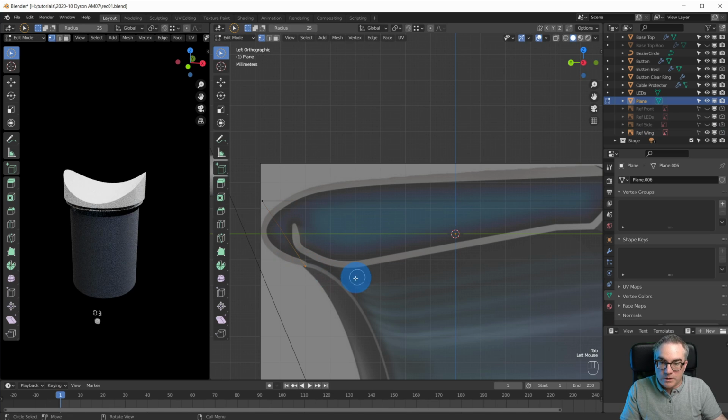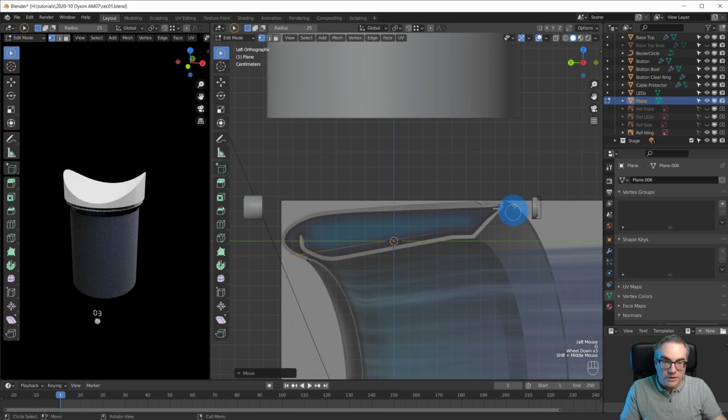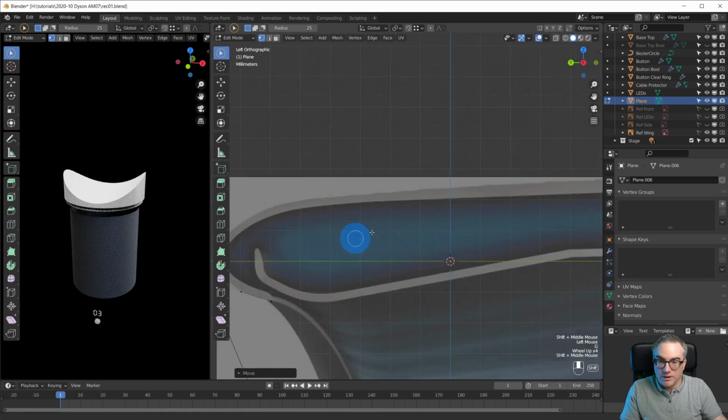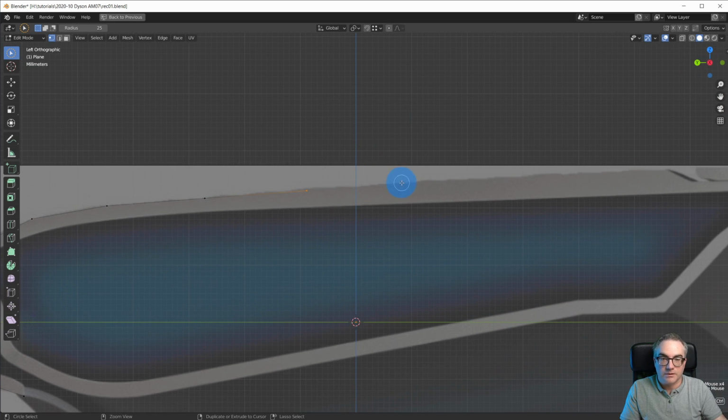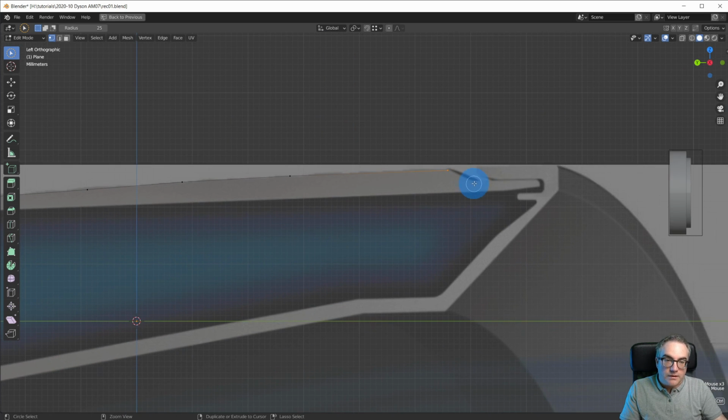So let's do this. Go into edit mode, place this guy here, and this one here, and then we're just gonna build up this wing shape with vertices. So we start off with these 3, and we go extrude, extrude, extrude, extrude. Control right clicking works as well, so you can go like this. Okay. Go over here. Then we create this shape in here.